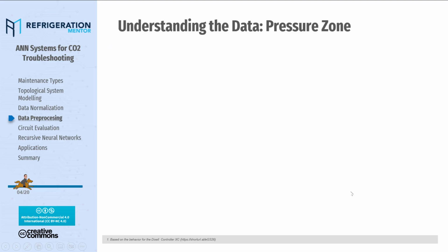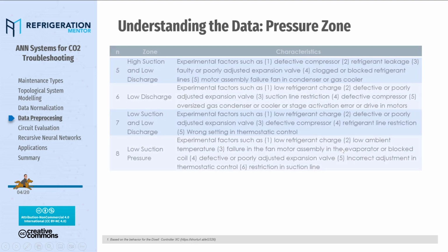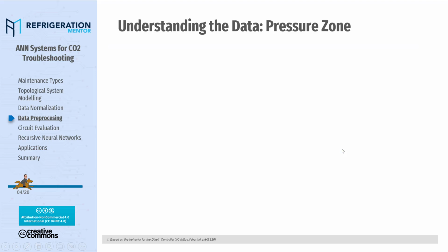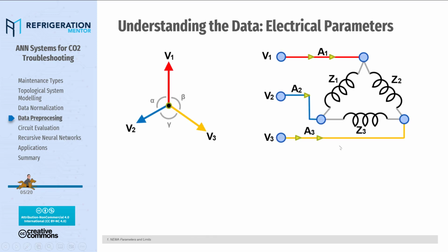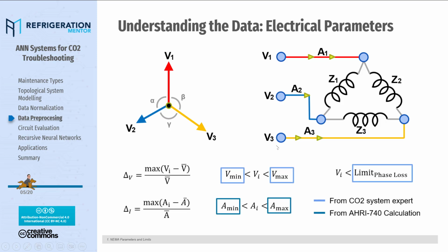As we know, most compressors are linked to an electrical motor to achieve their compression labor. So imbalances in the load of the electrical motor can cause some effects on the current consumption side, and imbalances in the voltage supply can cause some undesired imbalances.